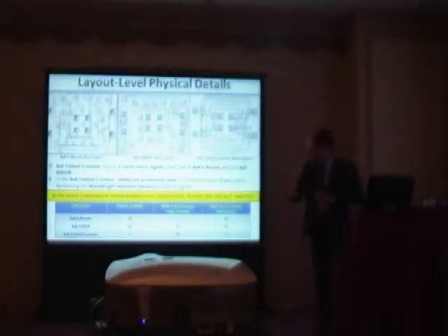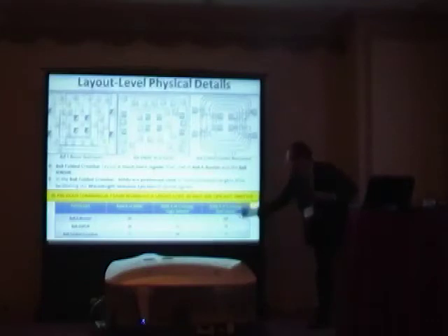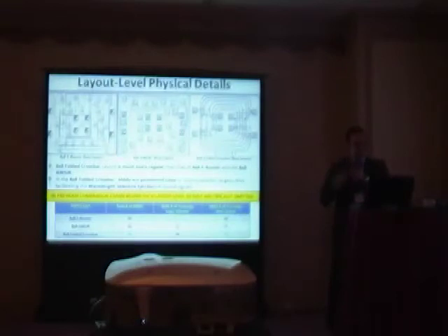Notice that the 8x8 lambda router counts for the maximum number of micro-resonators. Instead, the crossbar has the minimum number. In the critical path insertion loss, for the logic scheme, the 8x8 lambda router counts for the minimum number of crossings, and the crossbar the maximum, 18. But when you translate the logic scheme into its physical implementation, the surprising situation is the opposite. In fact, the folded crossbar counts for the minimum number of crossings, and again it's 72 in the 8x8 form. This is because of the mapping on the two-dimensional surface.